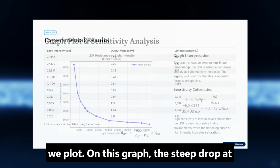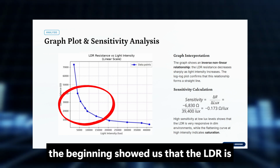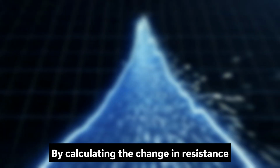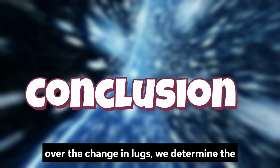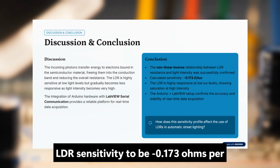When we plot this on a graph, the steep drop at the beginning shows us that the LDR is incredibly sensitive in dim environments. By calculating the change in resistance over the change in lux, we determine the LDR sensitivity to be negative 0.173 ohms per lux.